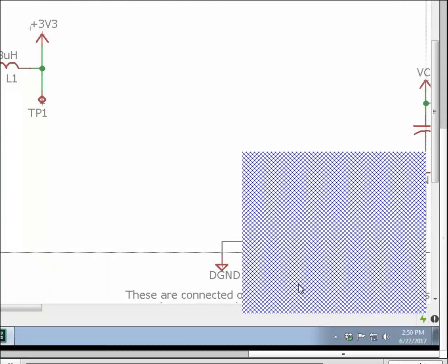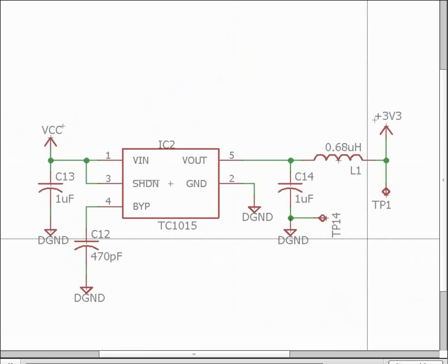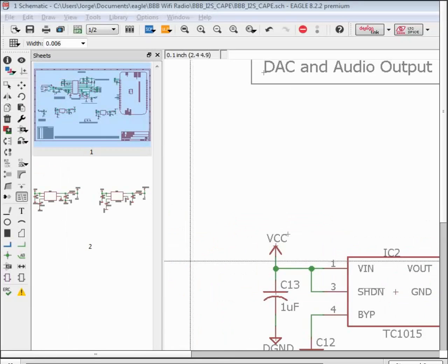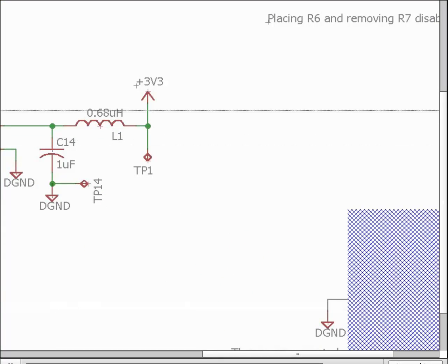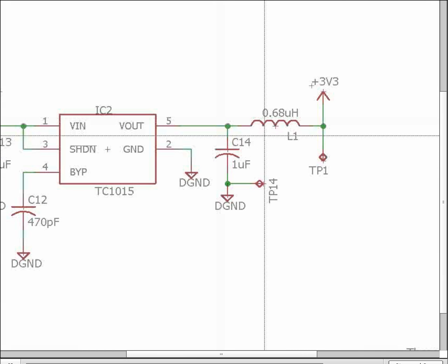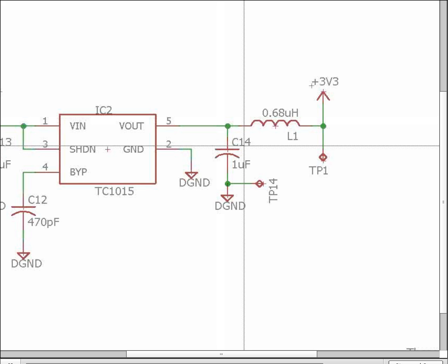When selecting and moving, how do you choose which one to select and move? There isn't a list. What ends up happening is you do the group cycle select. Wherever anything overlaps, hold down Alt and left click to cycle through the nearby items. If you're using one of the modal commands, then you use the old style cycle select, where if Eagle isn't sure, the icon will change to look similar to the move command, and you right click through the nearby items to cycle. It doesn't pop up as a list. You're basically just right clicking and left clicking to cycle through the nearby items. The list option sounds like a good idea, though.